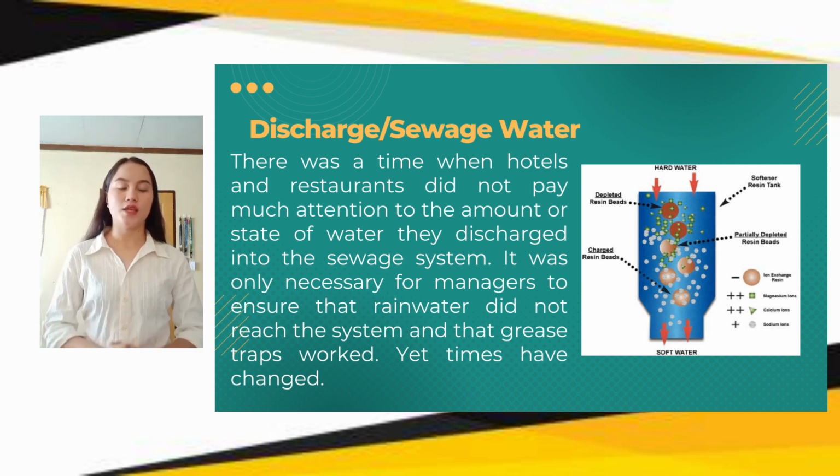So ion exchange can be used to remove hardness. Ion exchange replaces calcium and magnesium with a non-hardness cation, usually sodium in water softening, in a solid interface or matrix through which the flow passes. Calcium and magnesium in solution are removed by exchange with sodium.